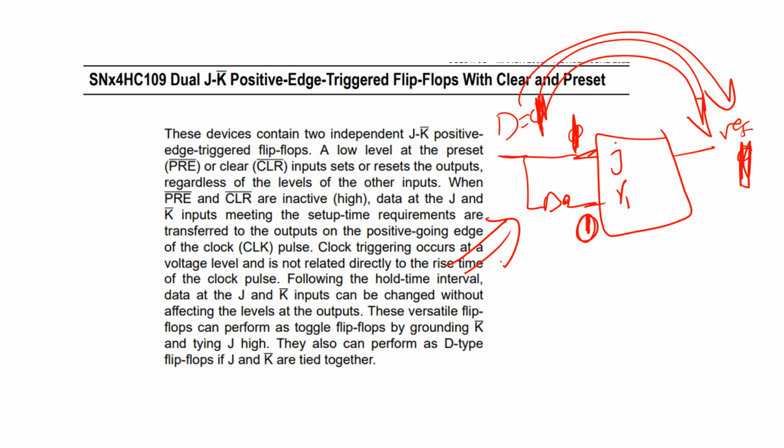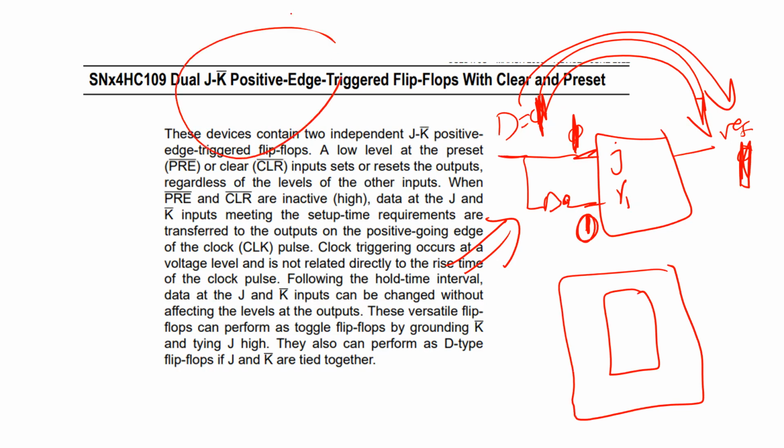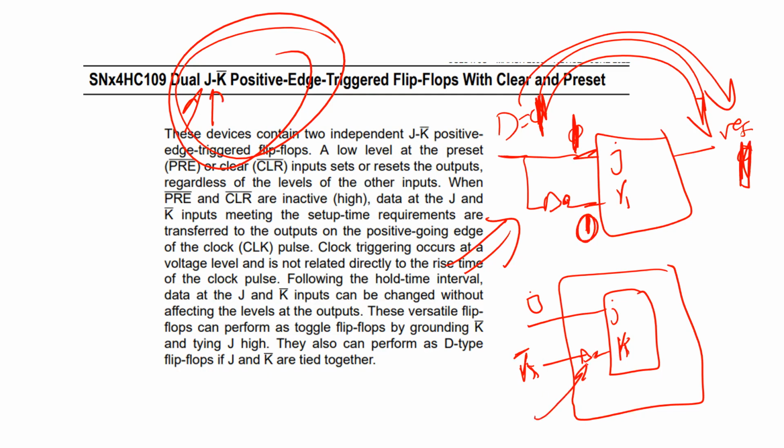However, the flip-flop we have in this lab is not JK. It's JK prime. You can see it like there is an inverter here already. So you input K prime here, and this is J and K. You got what I'm saying? Because it's not JK, they put an inverter here. Again, when you find another chip that has JK, it doesn't mean all of them are this way, okay? But they put an inverter here, because there is already an inverter here.